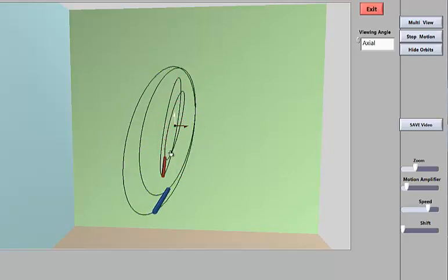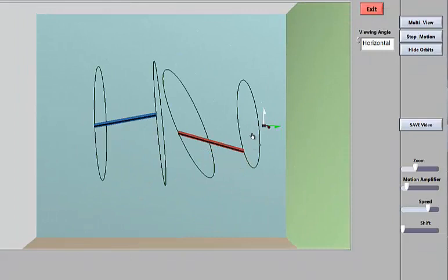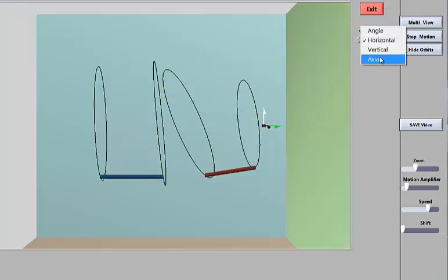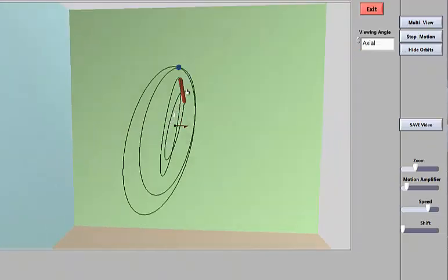But the red one, you can see that the outboard of the shaft, if we go to the horizontal, is moving a little bit lagged behind the inboard, and more importantly, when we go back here, it seems to be very flat responses, and the flatter the lines get, the flatter the orbits get, the more likely it is to be misaligned. Whereas the more circular it becomes, the more imbalanced it is.